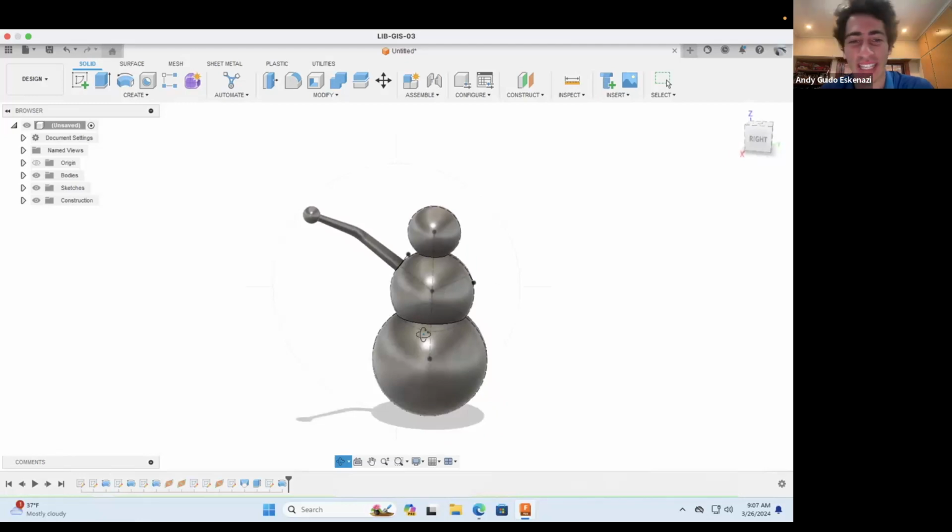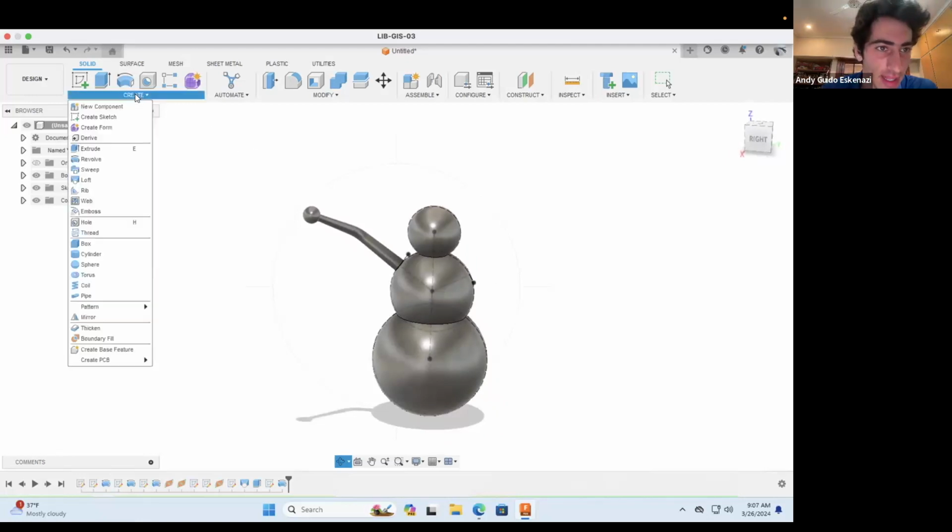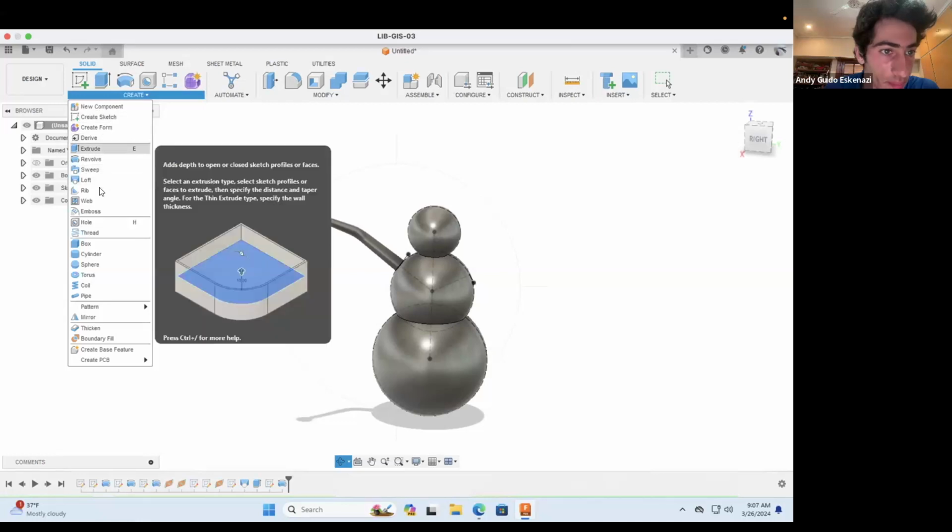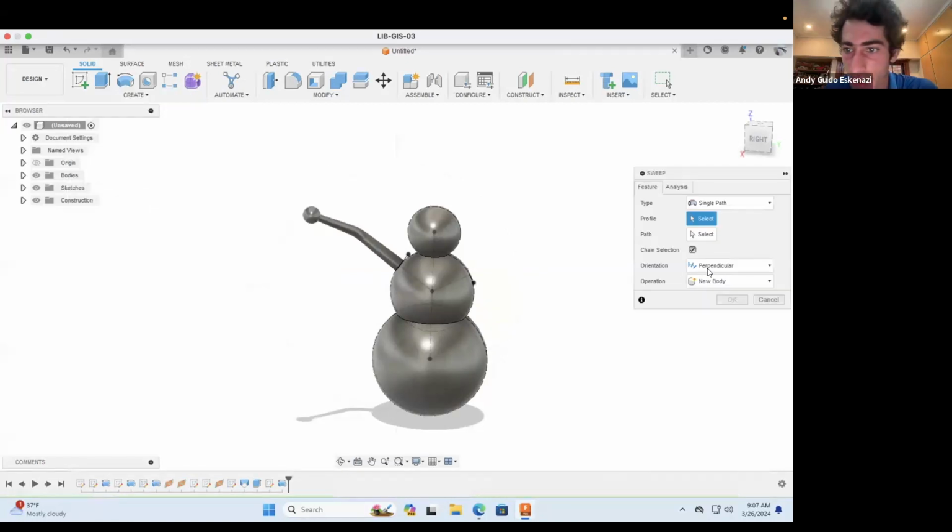So we're gonna do the exact same thing in there. There's another command, if you look in here, that's called sweep. Sweep is also something similar. That is, you can do like a single path. It's very similar to loft. The difference is I cannot give it this taperness that I have in there. I was wondering whether there was a command in SolidWorks where you could potentially do it, but I'm not going to use that now.